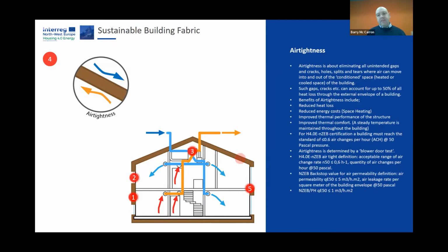The air tightness we talked about very briefly there again, but just to say about it, the standard for passive house is 0.6. It's actually not as hard as people think to make buildings airtight. At a high level, if your construction is masonry, then a lot of your air tightness barrier will be plaster. So it's a very cheap product. It's getting done on site anyway. You just have to have a little bit more thought about the sequence of what goes where and when it goes.